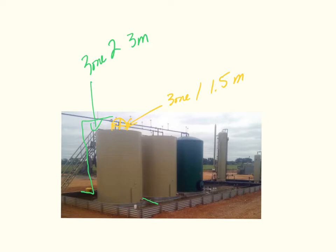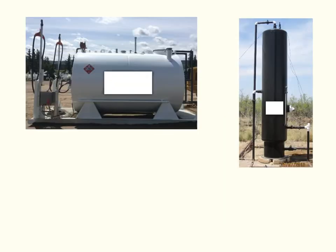And so the 3 meters all the way around the tank and to the top of the dike wall, whatever the top of that dike wall is. Now, it's important to note that the dike wall isn't necessarily going to be 3 meters. In my experience, they're a lot less than that. But the Zone 2 location does extend to the top of that dike wall.